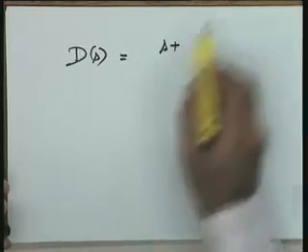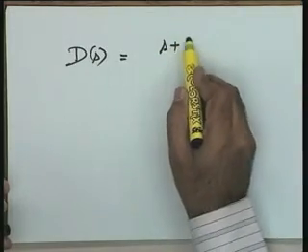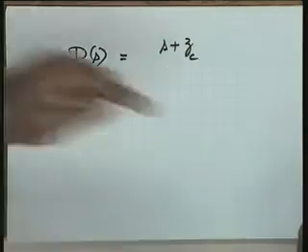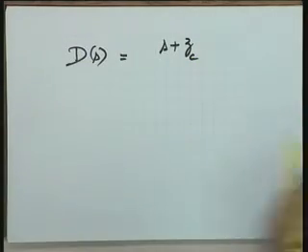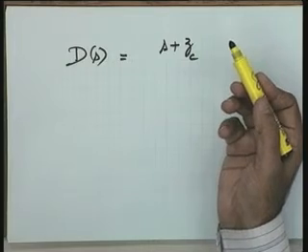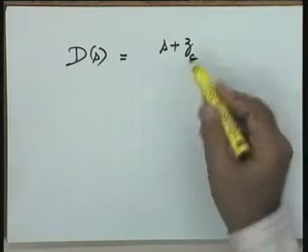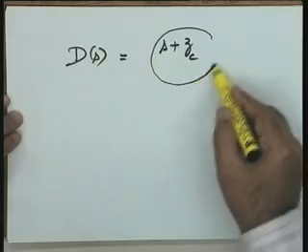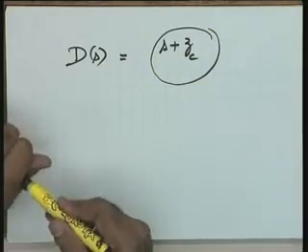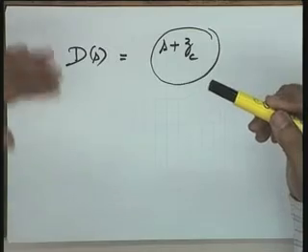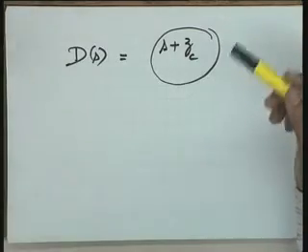Now a definition, a very important term used in the literature. You see that D(s) equal to s plus Zc means an s plus Zc compensator has been added to the system. It means, as you have seen in the process of calculating the Kv, we have added s plus 3 to the system. Now come to the physical realization of D(s) equal to s plus Zc. You see, as we go to the frequency domain, it will become more clear.